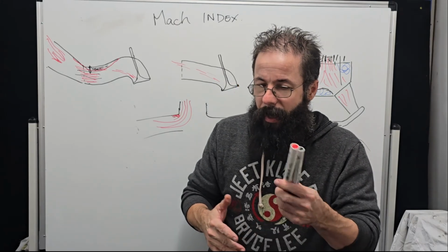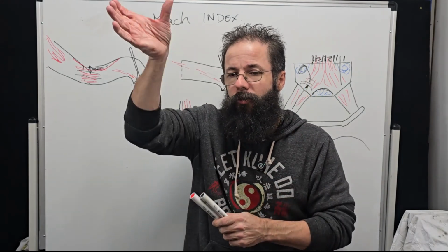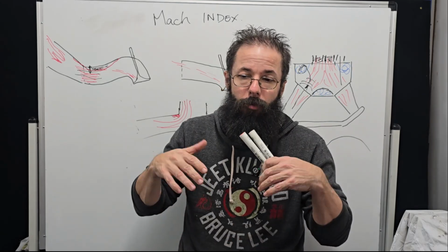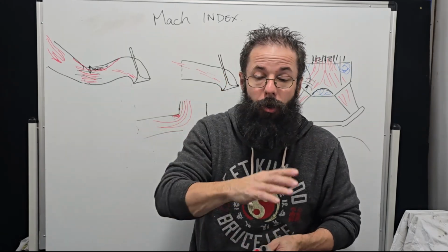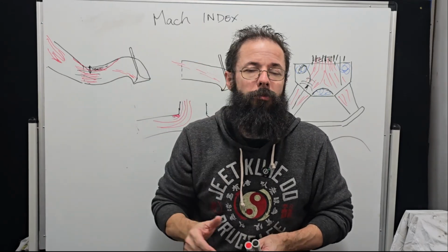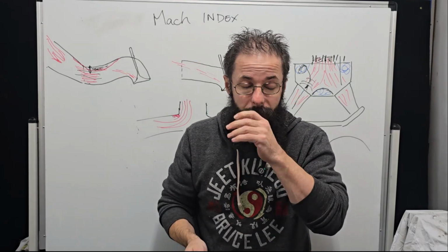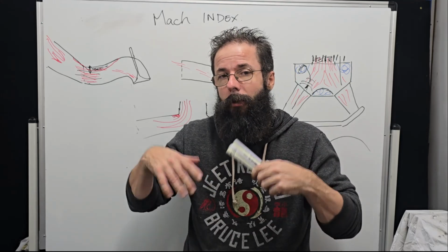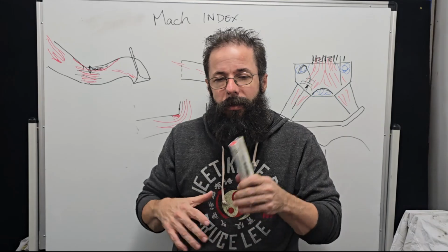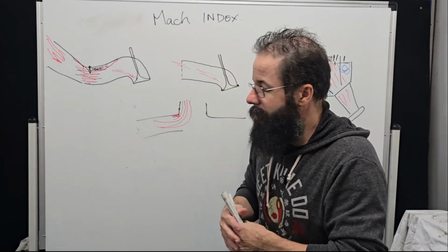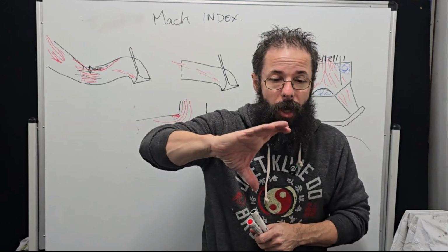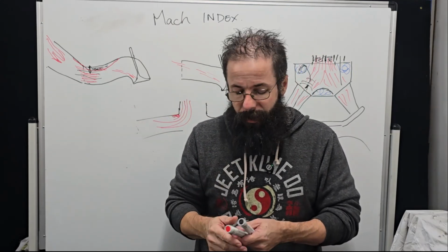So when you're looking at curved runners, you've got to understand what's happening with the air, and how much more restriction those curves are creating in the induction. So you look at a lot of OEM, they'll wrap right around because they're trying to get induction length, but they're also creating more restriction. So again, it depends on how they design it. There's little tricks you can do. I've seen some really, really smart guys out there now actually designing proper air induction systems.